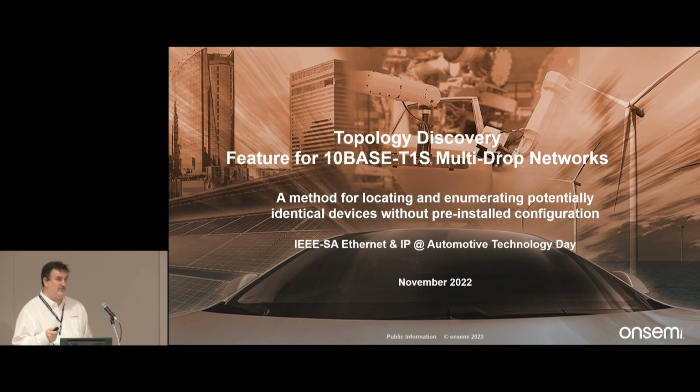But I'm here today to talk about a new feature for 10BASE-T1S, which is called Topology Discovery. Topology Discovery is a feature that allows you to measure the physical distance of two nodes on a multi-drop network, which is also called a mixing segment in the IEEE 802.3 terminology.